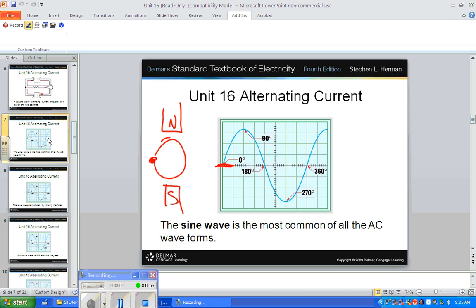Okay? And as it rotates up and gets to this north point, at that instantaneous point, in that one precise little slice of time, it's very near the north pole and it's very nearly moving directly across it. So it's going to create the peak voltage. That point right there.